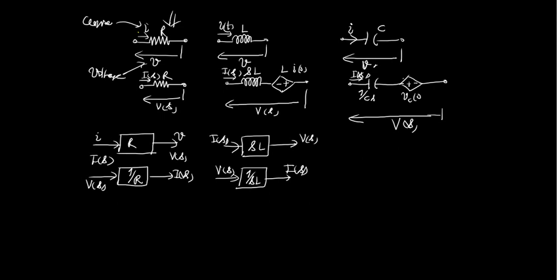Similarly, if you have a capacitor and you are giving a current into it, let me write in the Laplace transform domain, otherwise you will have to take the help of integral or differentiation. Is is there, you are giving it here, and the impedance is 1 by SC, so the output will be the voltage across this capacitor.